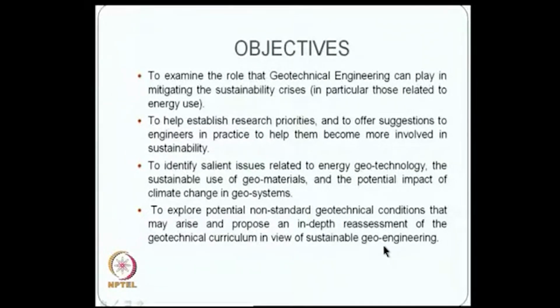geoengineering. What we studied so far in the ground improvement area is that, for example, if there is a civil engineering structure, earlier people were going for pile foundations. Of course, even now that is the order of the day, but then if they can be improved with, say, stone columns, a simple example, that is a big difference, like, for example, the consumption of carbon in the case of cement and steel is much higher, whereas you are trying to use some sort of stone or other aggregate materials in the case of soft soil when you want to increase the bearing capacity of soil.